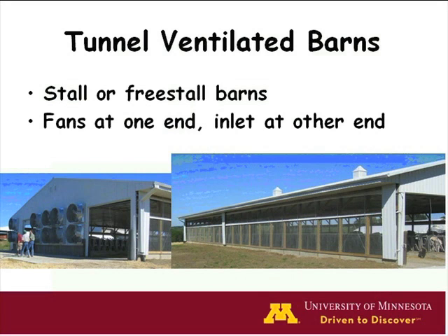And when it gets really warm, the curtains will go down on the sides. The door on the end with the fans that's showing would be closed, and the other end is kept open, and those 10 fans blow out, and that barn then becomes a tunnel with fresh air coming in on one end and blowing out the other end as part of the tunnel ventilation system.